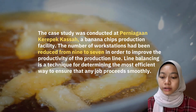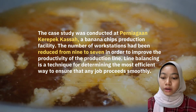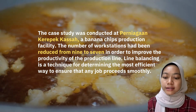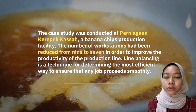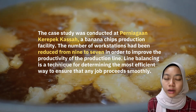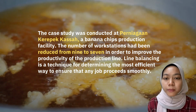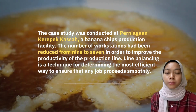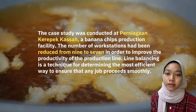As a conclusion, throughout this case study, the objectives, which are to propose a way to improve the current layout of the facility and to improve line efficiency through the use of line balancing, were achieved. Students are also able to identify the problems that occur during the process of making banana chips at Perniagaan Kerepek Kassah. The number of workstations had been minimized from 9 to 7 workstations.